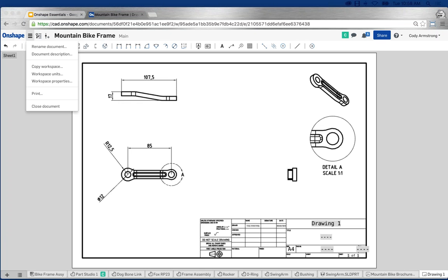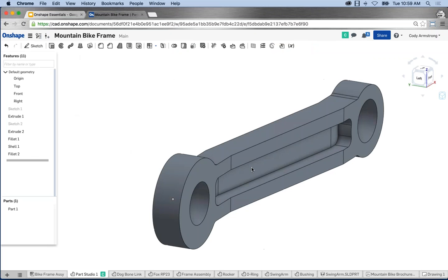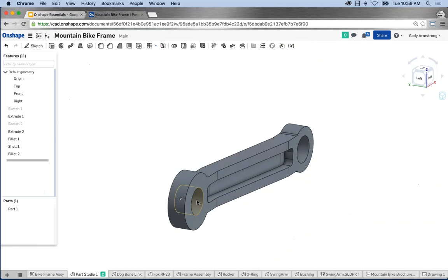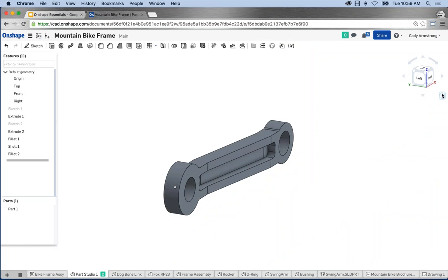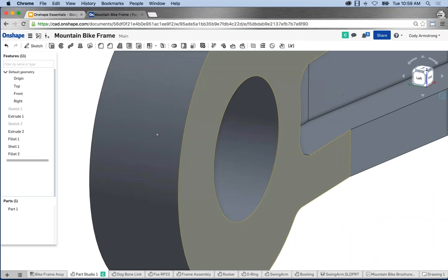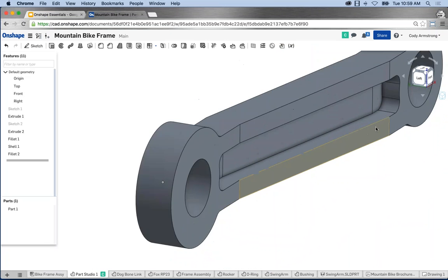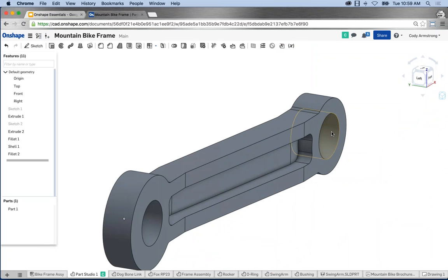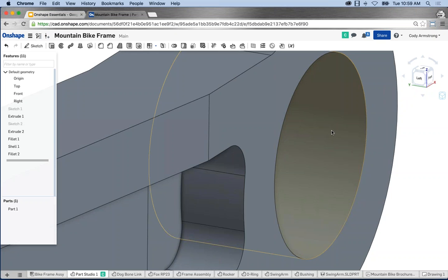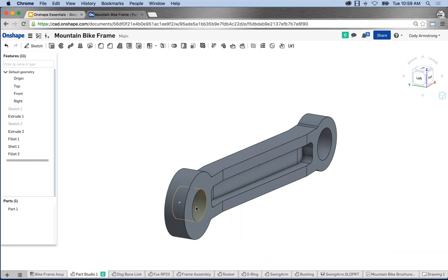I use this sketch to create items from molding, and I've not progressed to assemblies. I would like to see how I can zoom in to examine the details of locations as a whole. If you're looking to zoom in on a specific feature in your part, scrolling in and out is what I recommend. You scroll in and out to zoom in and out. Now, we do have other tools, like I mentioned, the zoom to window. You could draw a window around your location of holes, and it will zoom into that. So that's another method that you could use to highlight or zoom in on certain things. But in scrolling in and out, remember wherever your cursor is, that's where it zooms in at. So as I scroll in, make sure to move my cursor over the thing I want to zoom in on.